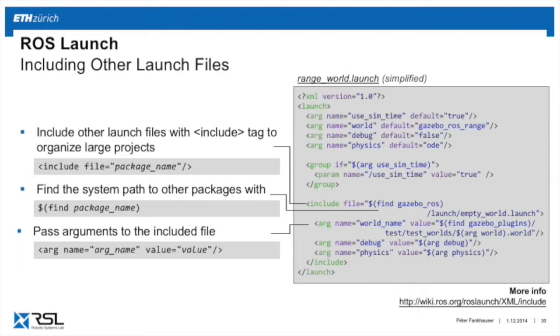Importantly, in ROS, don't use absolute file paths, because if you give it to a friend, they might have a different username, etc. So what we always do is relate it to a package. In this case, it says find and then the package name I've written here. This gives you the local absolute path, and then you would be in the launch folder, the empty_world.launch.